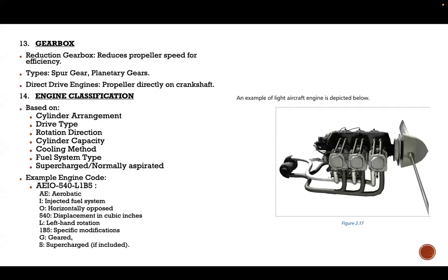Even if we are flying at 10,000 feet, by using a turbocharger you'll have the air density of whatever you can get at 5,000 feet. So when you go to 15,000 feet, you'll have a charge density of whatever you'd get at 10,000 feet. This gives us another 5,000 to 10,000 feet of added advantage. That is why we use a turbocharged engine. When you talk about this, we have a turbocharger, or we also have a supercharger. So we have two different things, a supercharger and a turbocharger.